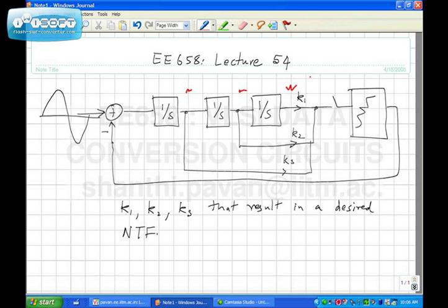Finally, you're going to design an op amp, right? And the output swings of an op amp are determined by the supply voltage and how much VGS minus VT you have for the top device and for the bottom device inside the op amp and so on. So the bottom line is that the peak swing at the output of each integrator cannot go to arbitrarily large values in practice, because they have to be limited by the supply.